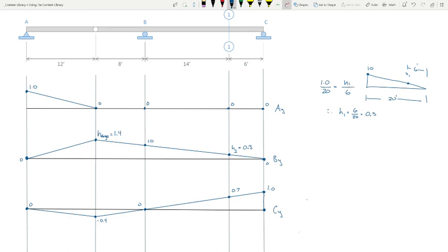But if I move away from B and stand on that hinge, that's an even worse effect on that supported B. It also tells me that if I stand on the hinge, I got some uplift issues at C to worry about, right? Because C's got to hold down, right? So the influence line tells me that I better design C so that it can handle some uplift, right? B's probably going to be my worst case design in terms of just sheer amount of load, right? And with support A, as long as there's no load over here, I got nothing to worry about. It's kind of crazy stuff, isn't it?